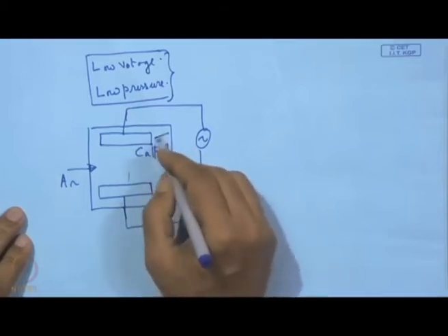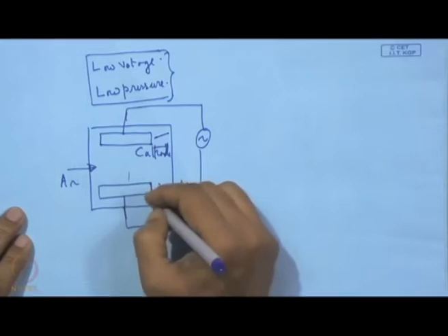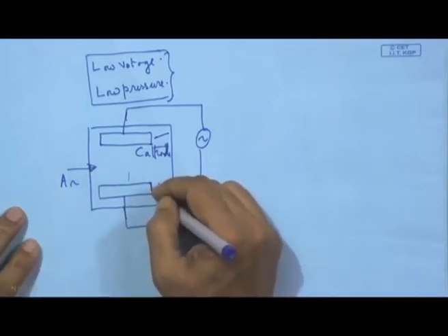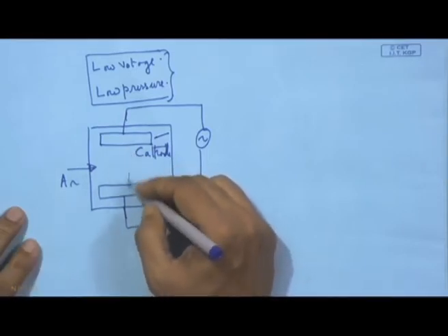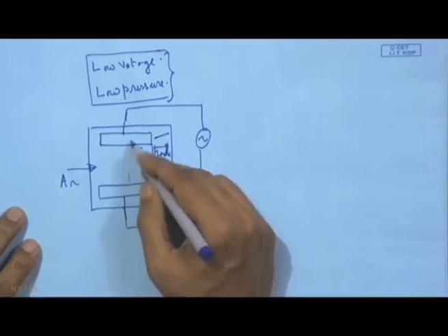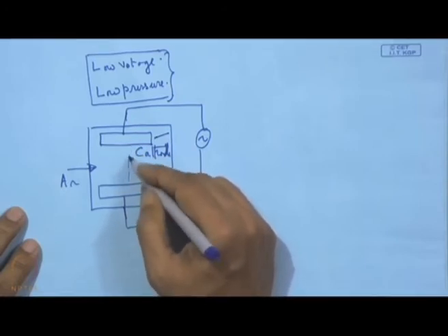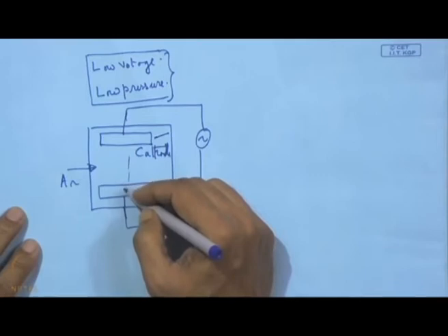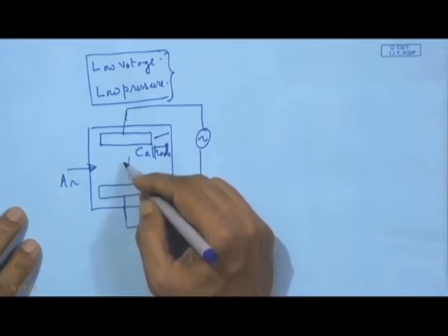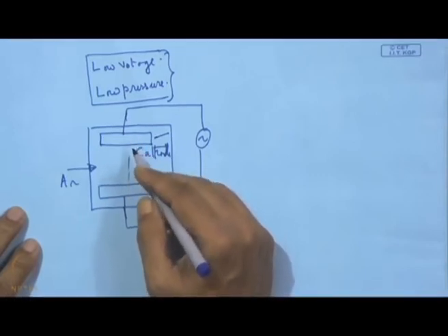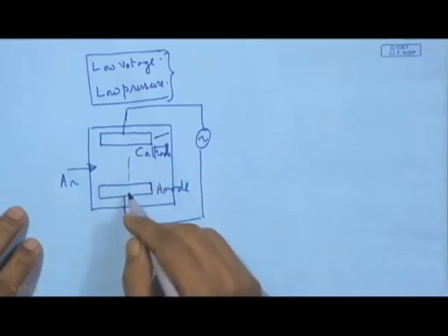So, this is the electrode which is actually the target, and this is the other second electrode, and within that, in between, in this inter-electrode space, that will keep on oscillating and swinging, and through that there are more chances of hitting not just one argon neutral, but many more before they are really exhausted and lose their energy.